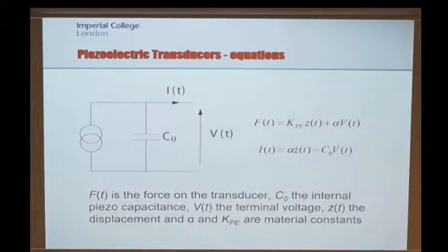And the overall force on the device depends on a spring type of expression, where we've got a force which depends on displacement, and then also an additional force which depends on the voltage that we see on this capacitor. So clearly we've got two effects here that are changing the force that we see on the piezoelectric material. We've got this inherent force of bending the piezoelectric material with no change in voltage. And we've got an additional force which comes about by the fact that we have a voltage on this capacitor.